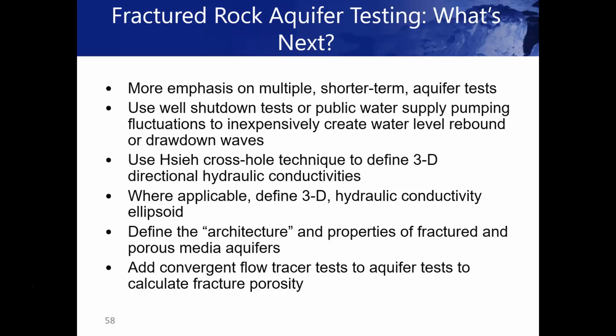Okay. I think by storage effects, do you mean well bore storage? That is water that's within the well bore. Let's say it's a 12-inch diameter well, there's a lot of water in there. And if you pump it at a very low flow rate, at least initially, a lot of the water that you're pumping out of the well is water in storage in the well. There are methodologies to account for that and take it into consideration.